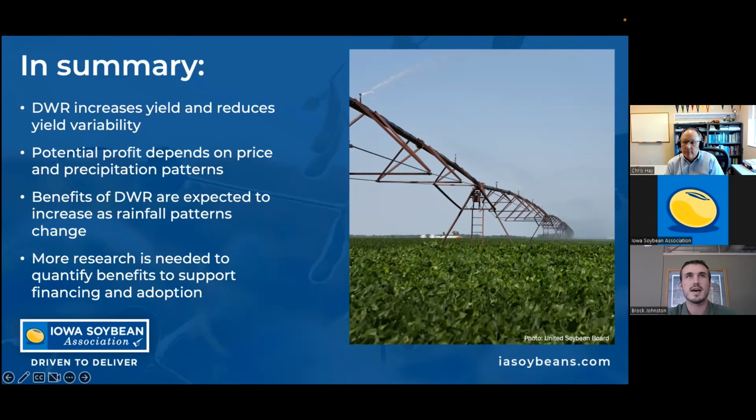And then moving into that water storage capacity, how big would a reservoir need to be to have that impact on the field? Yeah, so it looks like the sweet spot is about 4 to 6 inches of water. 6 inches is better, 4 inches is pretty good, relative to the area you're irrigating. So if it's about a quarter section, you're probably looking at about a 4 to 6 acre surface area reservoir, assuming about a 10-foot average depth. It's going to vary a little from site to site, but that's at least an idea.